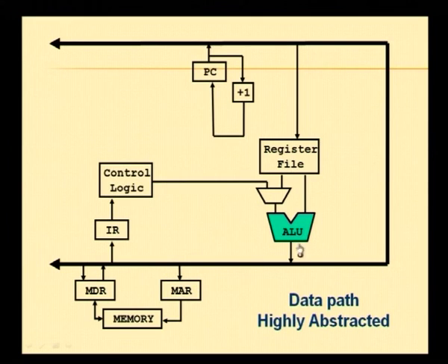Now, as part of the processor we said there will be an ALU, or arithmetic logic unit, and there will be a register file which consists of multiple registers, and then you will have input coming into this ALU from the register file. The ALU would do the actual operation, some arithmetic or logic operation, and the output could be stored either back into the register file or the output may be stored in a memory.